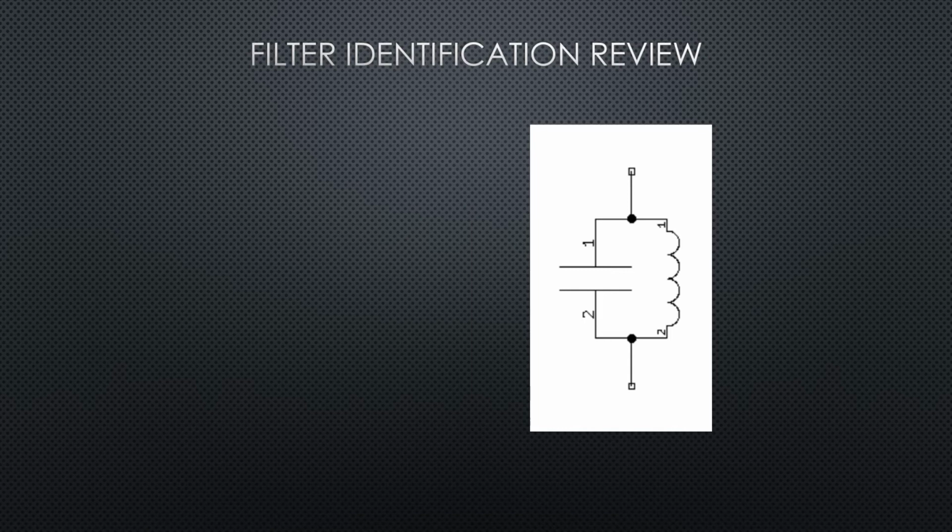So if your denominator is approaching zero, it doesn't really matter what's in your numerator. In this case, you'd have the product. But as the denominator approaches zero, the impedance of that tank will approach infinity. So at resonance, this circuit will have very, very high resistance.